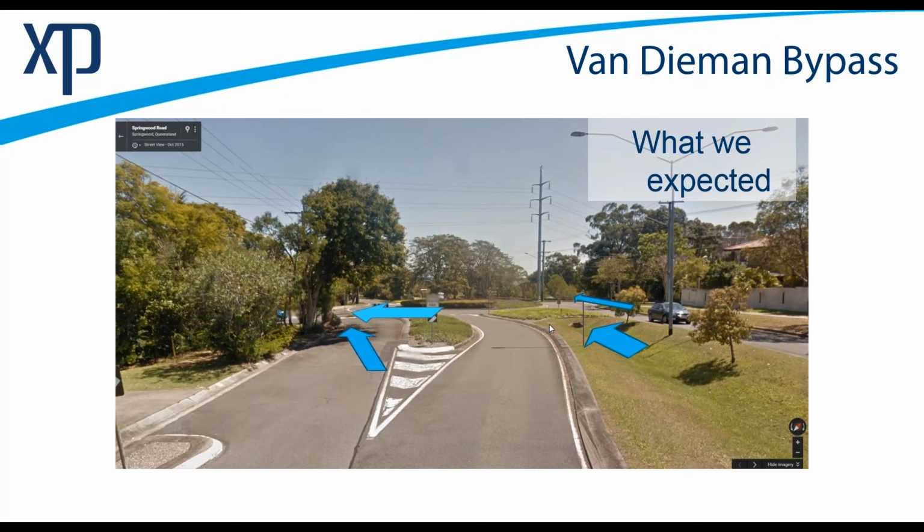Now, the way we approached this project, I don't have the model to alt-tab between, but the original design was done using the rational method completely before we went and had a look back through it, because it was way over budget at 3 mil, about 1.2 million more than budget. The flows coming down to that big escarpment were via this road. So the roundabout, and if you were to eyeball and make an assumption of where the flows are going, I would have said most of the flows, except for the lane going against you, was going down into the sag.